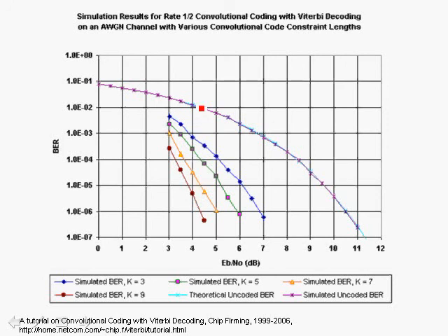So let's discuss this diagram. First of all, you can think of this diagram as plotting the bit error rate versus the Eb/N0, which is related to the signal to noise ratio. Eb is the energy per bit, and N0 is the one-sided noise power spectral density, typically in watts per hertz. Typically bit error rate curves are plotted against Eb/N0, which can be related directly to signal to noise ratio. We'll discuss this in a future topic.